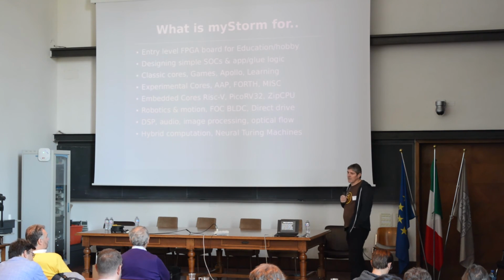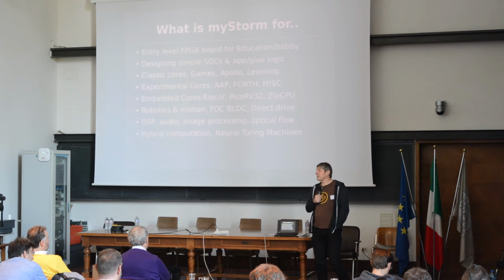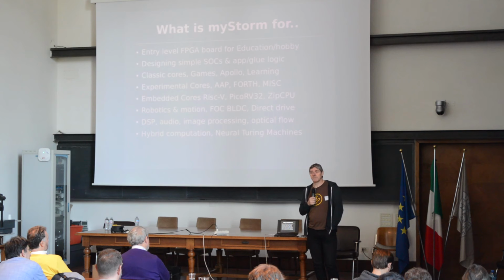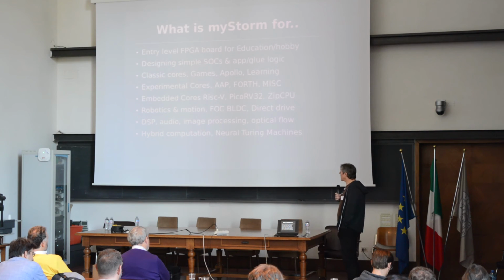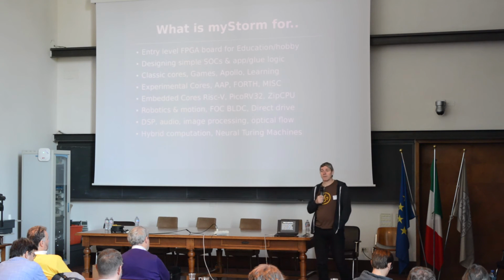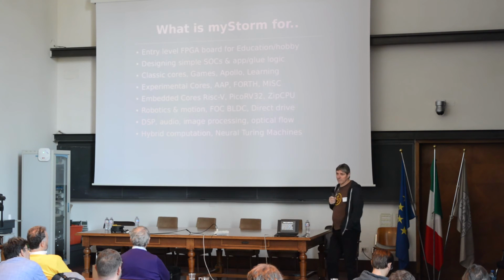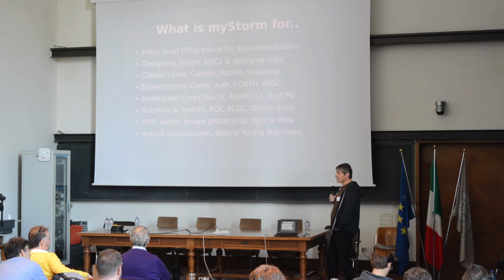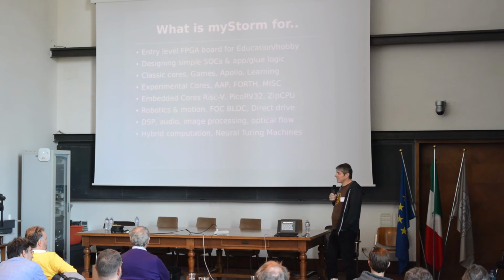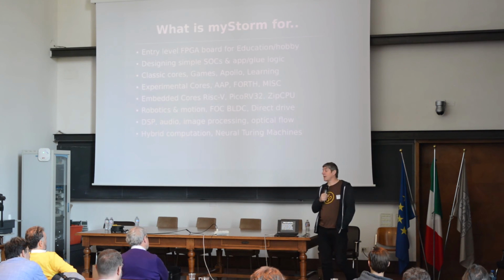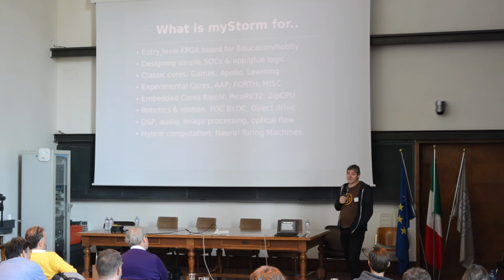Embedded cores and RISC-V, we've heard a lot about this this weekend. This thing's going to take the world, I'm sure. ARM probably aren't shaking in their boots, but they really should be. I think what we're going to see in the future is a RISC-V world, whether people like it or not. It's moving so quickly. You can do some very basic stuff, fitting it into this small amount of memory. Don't expect to be able to do a fully blown RISC-V implementation, but certainly something like the PicoRV32, as Clifford has shown. ZipCPU, which was really interesting yesterday. You can certainly fit that in this very easy.